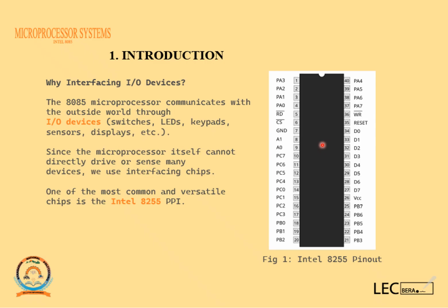But to take you through them quickly, all the pins you see starting with PA are connected to port A. All those which contain PC are pins connected to port C. And then we have PB pins, which are connected to port B. So we have a total of 3 ports: port A, port B, and port C. We are going to see how they are used.